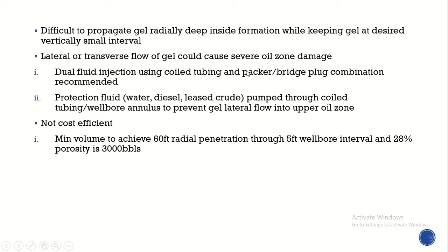Firstly, it is very difficult to propagate a gel radially deep inside the formation while keeping the gel at the desired vertically small interval. As for lateral or transverse flow of gel, it will cause severe oil zone damage.